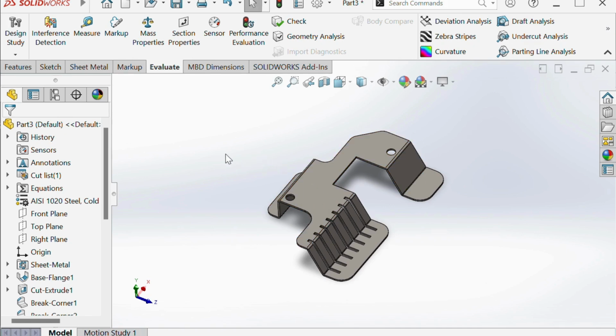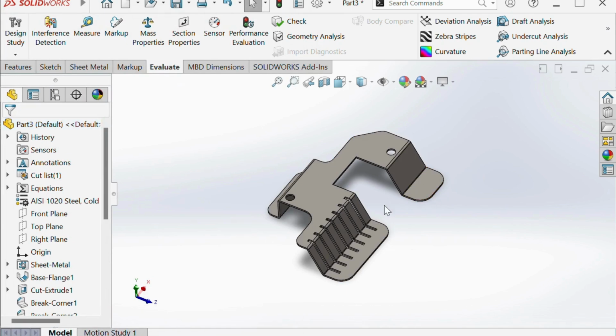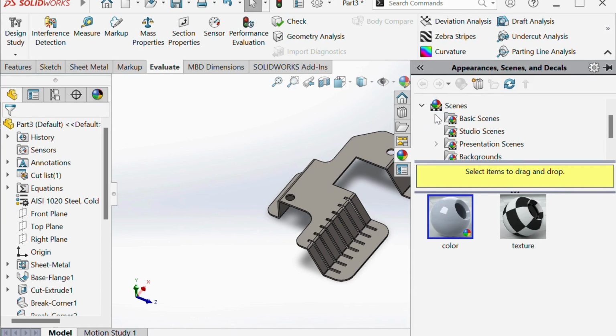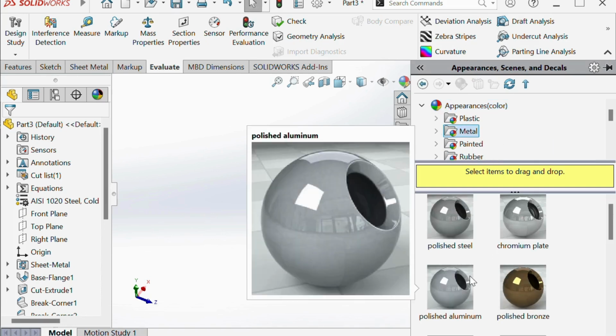We'll choose the material. What material is it? So this part is steel, that is mild steel, cold rolled. If you see the value, you have the density and everything for the CRCA mild steel. Click on apply and close. So now you're done making a sheet metal part. This is CRCA 2 mm thickness material.